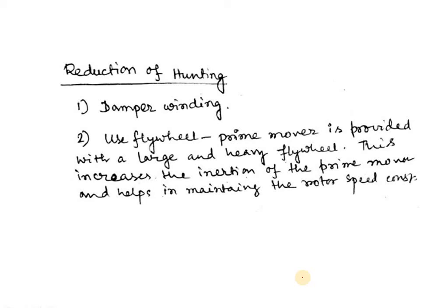So the reduction of the hunting phenomenon can be done by these two methods, that is damper winding, and another one is using a large flywheel.